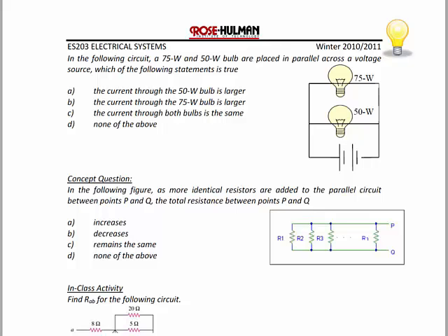One of the first things I want to show you is that we can have a battery symbol that represents a voltage source. You will see this when you do the Multisim simulations for some of your pre-lab circuits. This battery symbol is equivalent to a voltage source, where the longer line represents the positive and the shorter line represents the negative. Now, since all three of these elements are in parallel, parallel means same voltage.